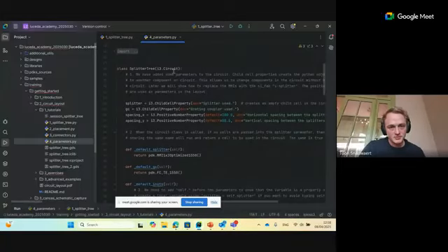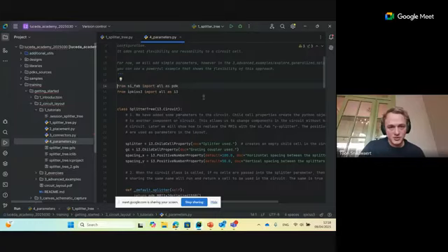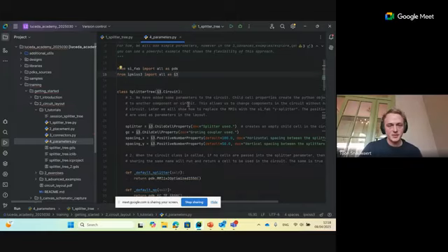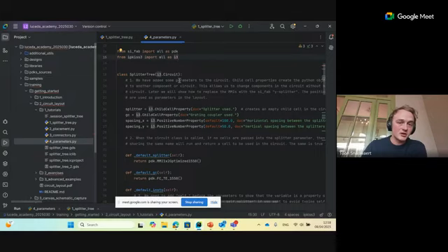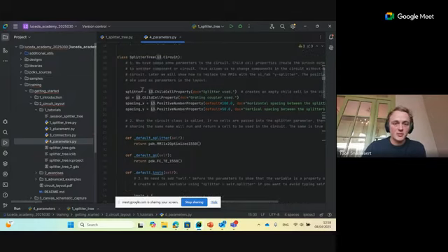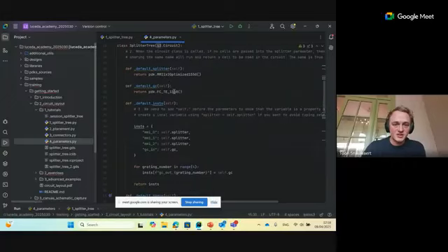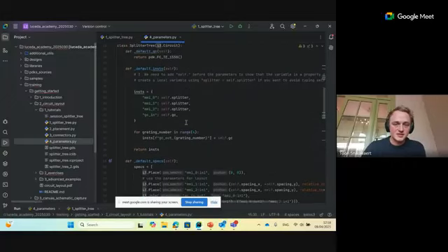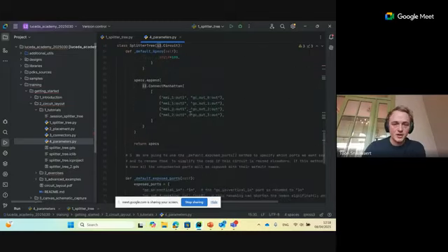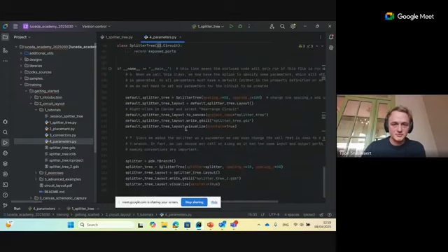Here we have the same way we always create a circuit: we start by importing the SciFab PDK, then we import the functionality of IPKISS, and then we can start by creating our class. We have our parameters here, our default methods for our parameters, then the instances and the specs, and also the connectors we add to the specs. And we have the expose ports. And here in the main program, we can create a splitter tree where we choose the spacing between the components.